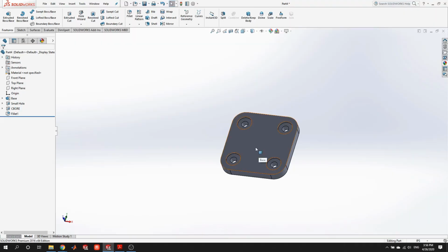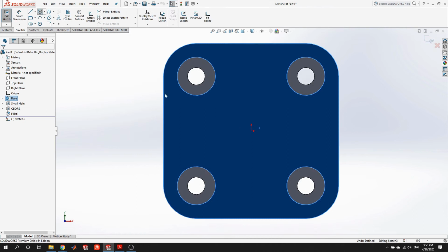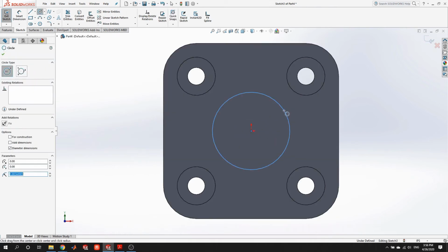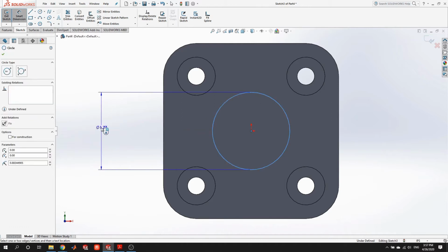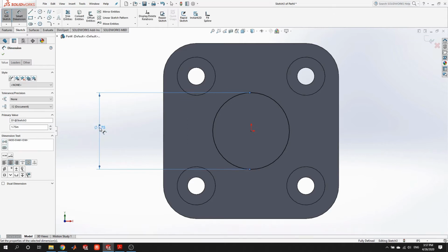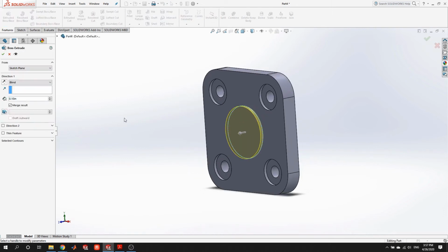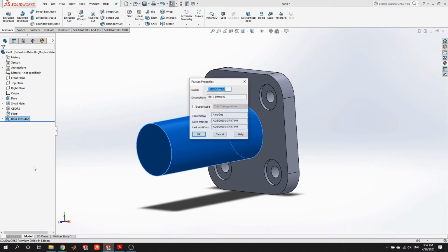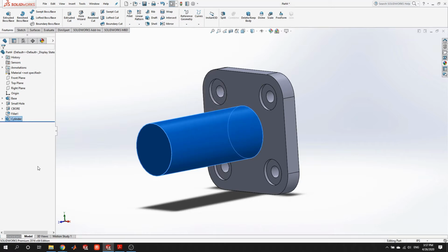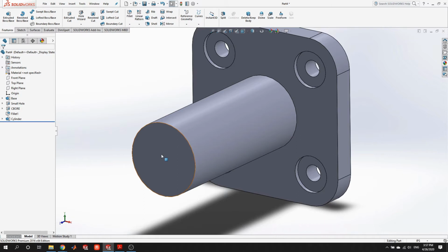So what we're going to do is add the sketch onto this face. We're going to snap a circle to the origin because that's in the center of the part. And it was radius 0.875, so we can do this, 0.875 times 2, get the diameter, exit the sketch, and we'll extrude this 4 inches out from the face of the base. Perfect. We'll call this cylinder.